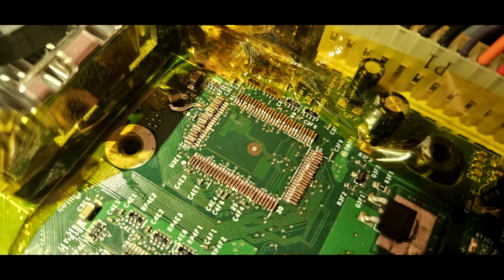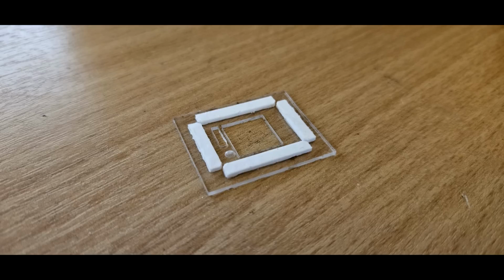So this is what I came up with. I got a bunch of thin pins and I soldered them onto the footprint on the Xbox side. The idea is that the interposer can sit on top of those so that the flex is the only thing that is contacting, and then I can apply pressure from above with a part such as this. I have deposited silicone onto this piece of acrylic.